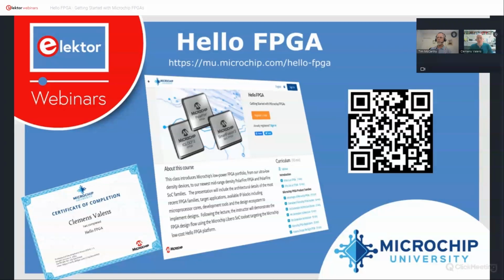I don't recall off the top of my head if we have a partner that has developed a USB IP core. You can check on our website on our IP page. The SmartFusion 2 and PolarFire SoC devices have a hard USB controller.